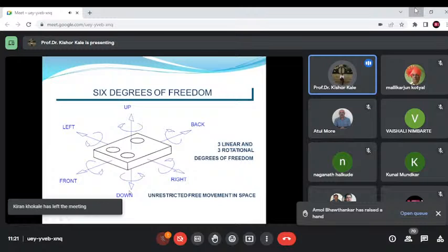So this is called 3D cloud points or 3D point cloud, both are the same. Some literatures call it 3D cloud points, or some call it 3D point cloud, but it is the same. It is the cloud of a number of points acquired, measured by the measuring machine, and these points are actually compared with the CAD drawing.